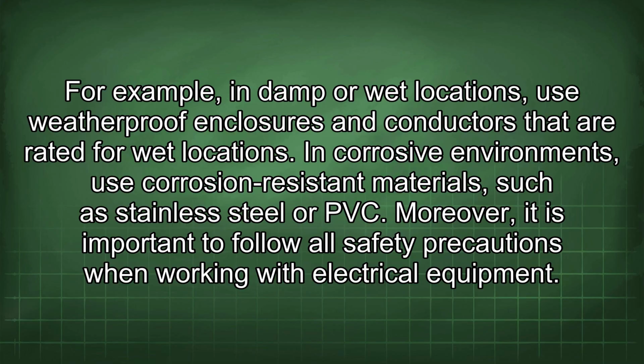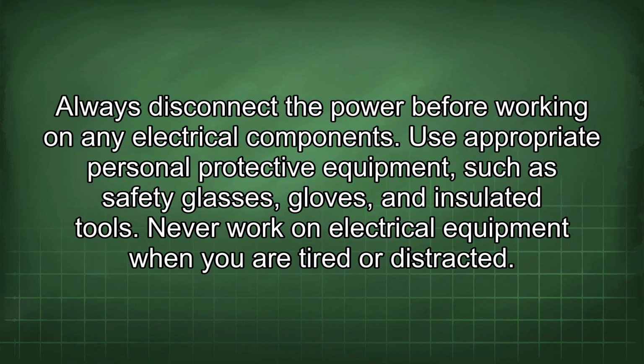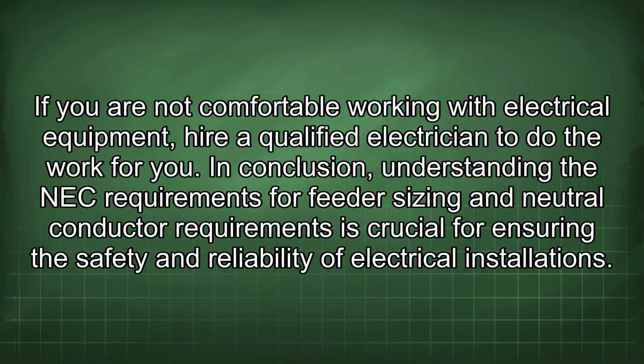Moreover, it is important to follow all safety precautions when working with electrical equipment. Always disconnect the power before working on any electrical components. Use appropriate personal protective equipment, such as safety glasses, gloves, and insulated tools. Never work on electrical equipment when you are tired or distracted. If you are not comfortable working with electrical equipment, hire a qualified electrician to do the work for you.